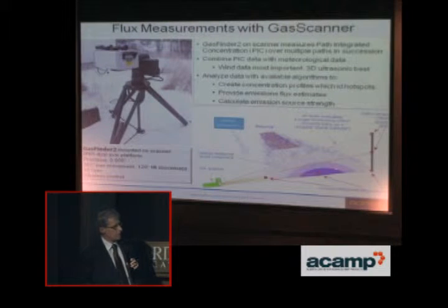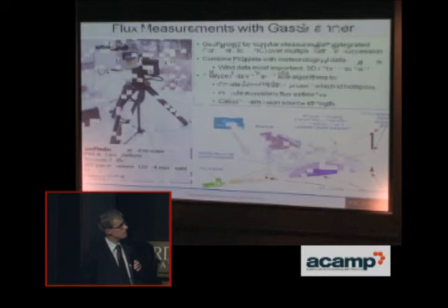By combining that information with meteorological, typically micrometeorological information, it's possible to create concentration profiles and calculate the flux of gas emissions from an area source.